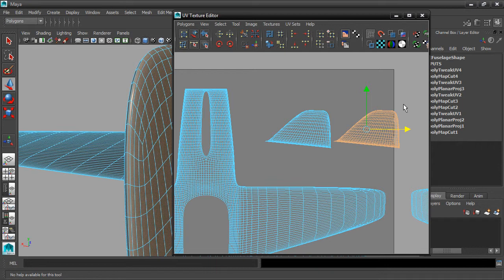And this accomplishes the same thing as rotating the manipulator. Choose the Scale tool. And then once again, hold down the J key. That'll give you discrete scale. And then drag until it flips. You don't want to go so far as to scale it to -2. You just want to scale it to -1. Now that's a perfect mirror image.